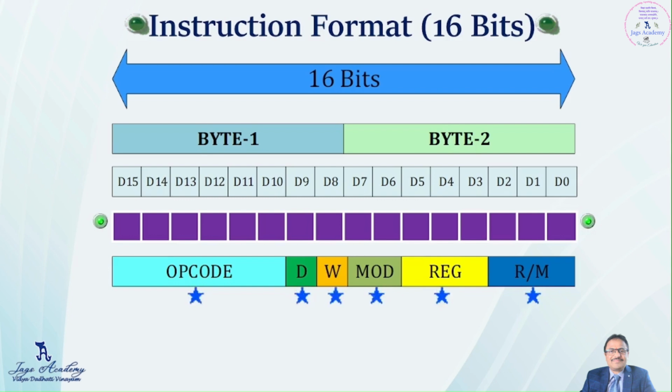It can be only in the bx register. It can be in the bx register and also the si register. While generating an address, I can use only the bx register alone. I can use bx and si registers together. I can use bx and si registers together along with some relative value. Right? These are the different ways of bringing in the data from the memory or putting data into the memory.